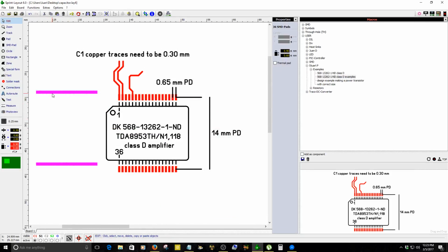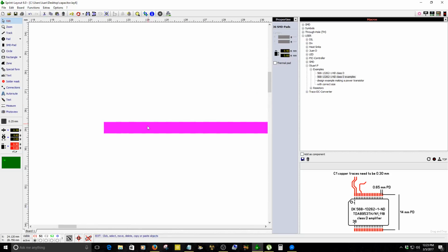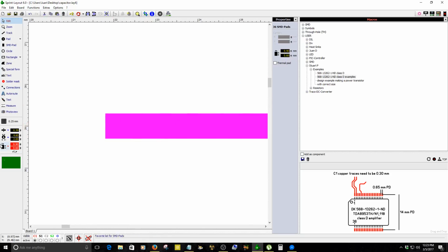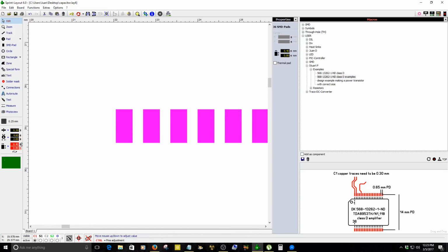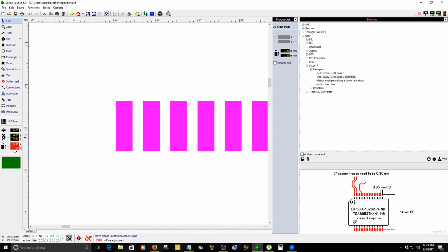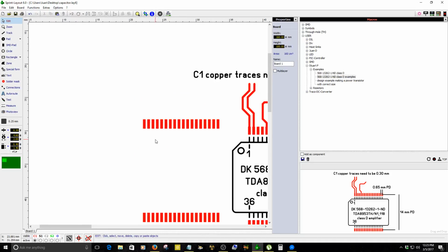And I notice here, I think I gotta change the thickness of the paths because they are touching each other, as you can see here. So I gotta change it here. It's 0.40 and, let me see, I think I can make it longer. I think it will be easier if I make them longer. It will make the soldering a lot easier that way.